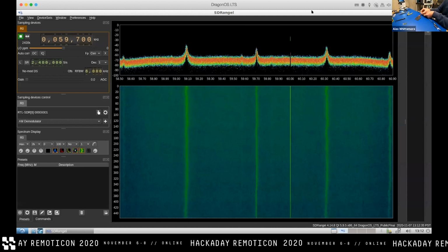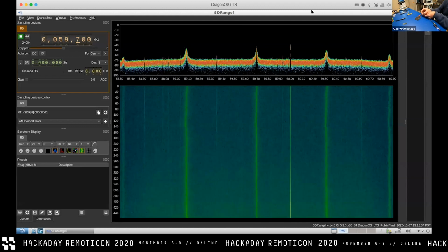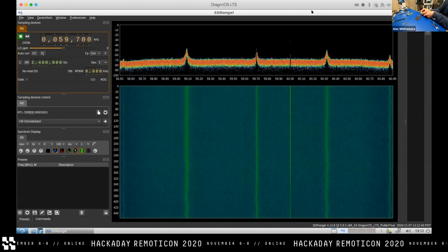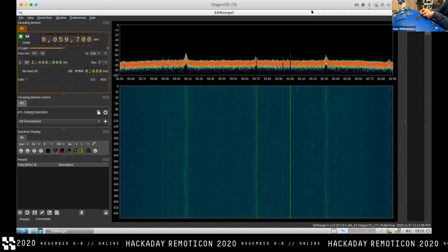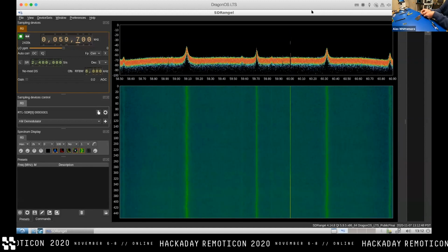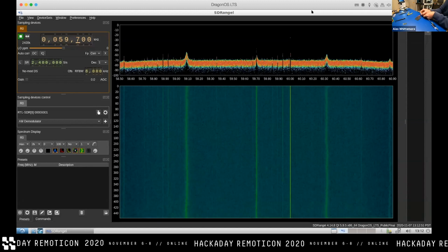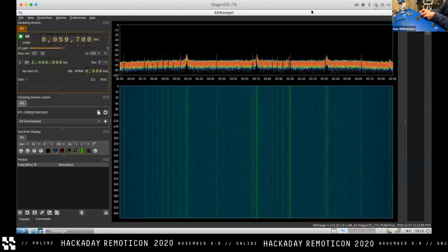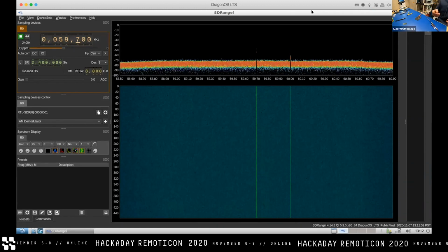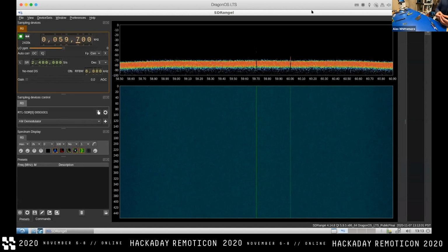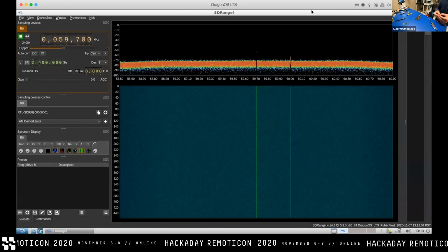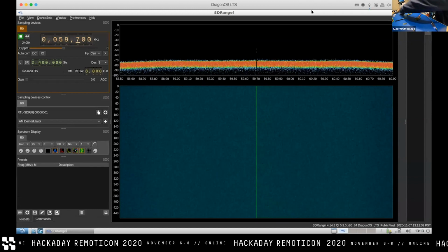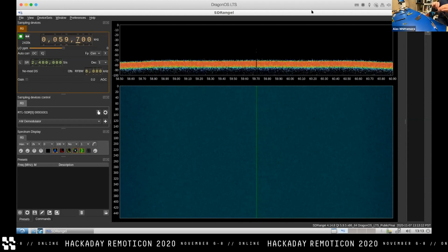So if we come over here and wave our probe in that spot, we see that really sharp line on that signal and actually some other harmonics going on in there that we didn't see before. So that's super interesting, and I haven't looked into what that might actually be. If we move around, we see some other nice sharp lines that pop out, and those are very clearly artifacts. And because we've got the spectrogram view here too, seeing in the time in the waterfall diagram what's going on makes things a little bit clearer when we have such thin FFT bins on this particular screen.